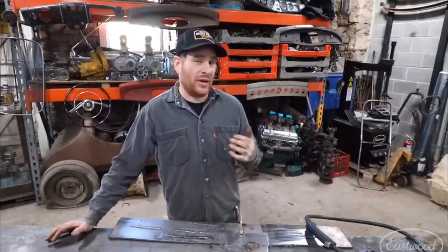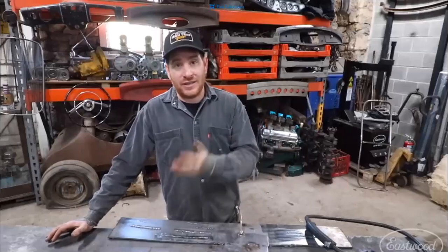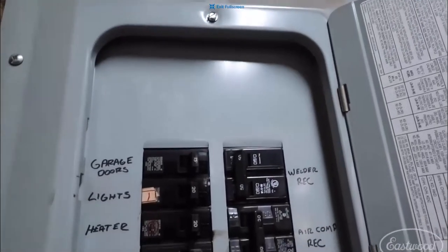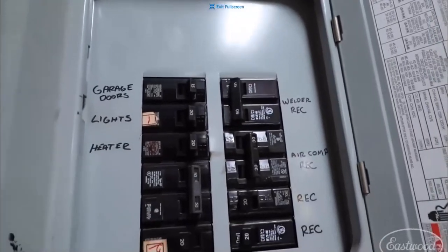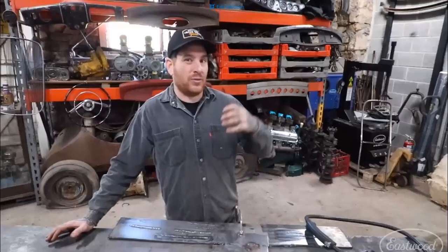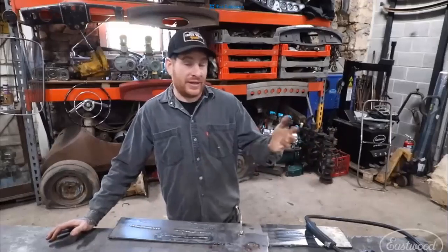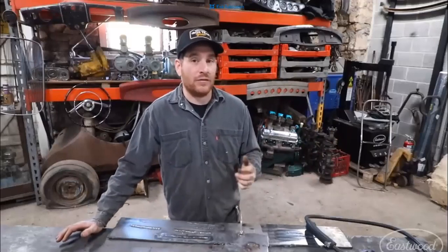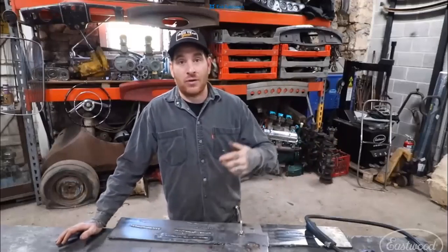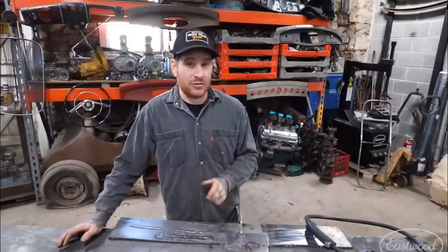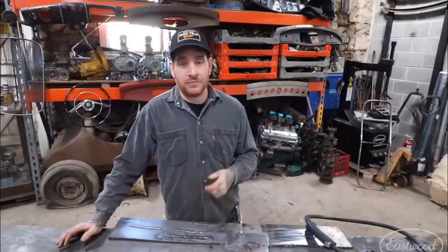That can actually handle a 30 amp breaker, but I have the TIG 200 for my TIG welder, which I think needs a 50 amp breaker because I tend to do long runs at close to the max of that welder. So in that instance, I want to put a 50 amp breaker in my shop, and that's what I have. If you have too small of a breaker, like you're trying to piggyback off of a 220 line that's maybe running some home appliances like your washer or dryer, then you may have an issue where that breaker is too small and you may be popping the breaker.